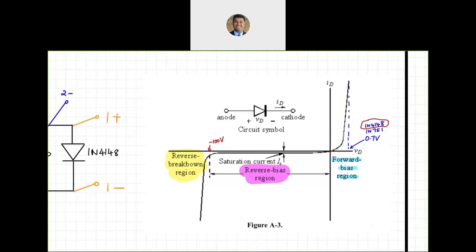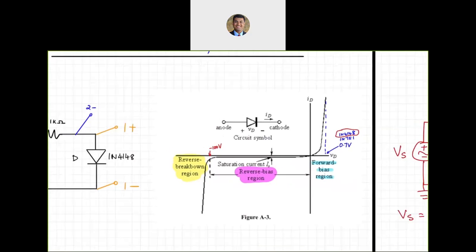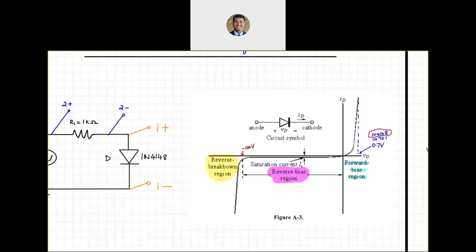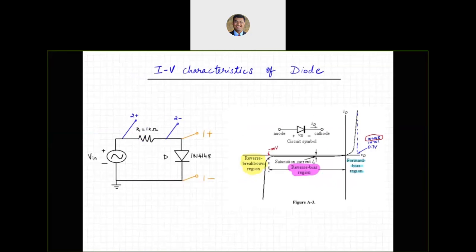Exactly the same way we have done that for resistor, capacitor, and inductor, it turns out we can get an exponential function to fit the I versus V for the diode. But that's going to be only for the forward biased region, because we are never going to be able to go to -100 volts using the Analog Discovery. So we'll have to settle for -5, or we can get to -10 by using the negative power supply as an offset. So we'll take a look at that as well in the experiment.